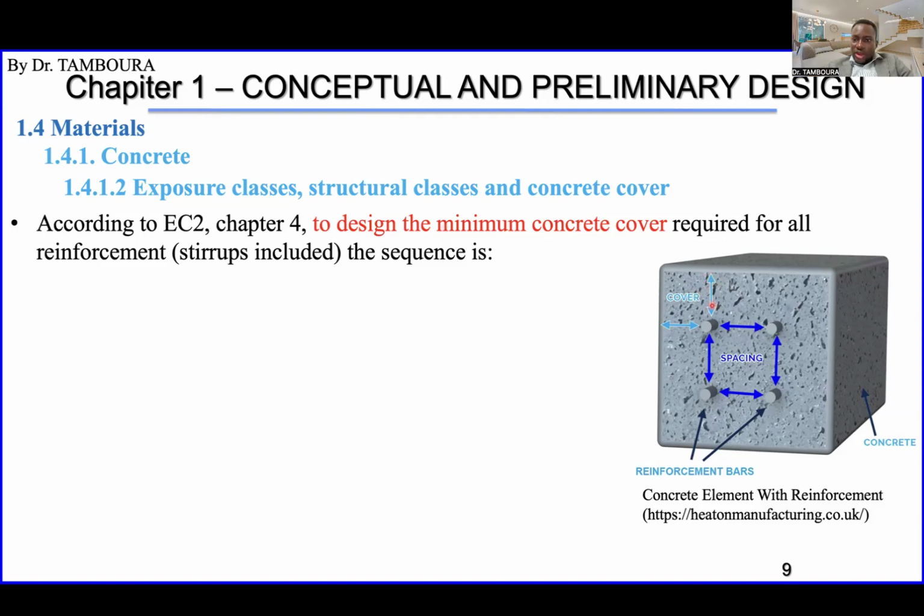Because this cover is important because it helps to protect this steel reinforcement bar from corrosion, and also it helps the bond between this steel bar and concrete, so that they work as a unit.